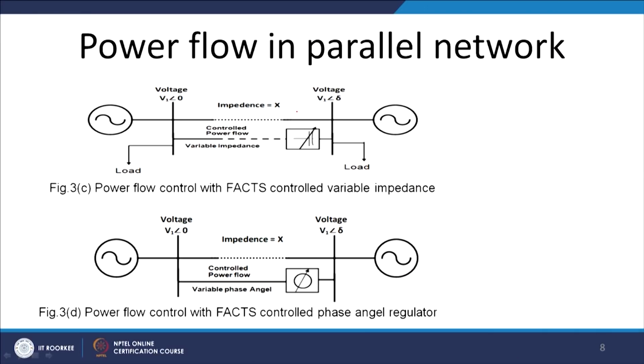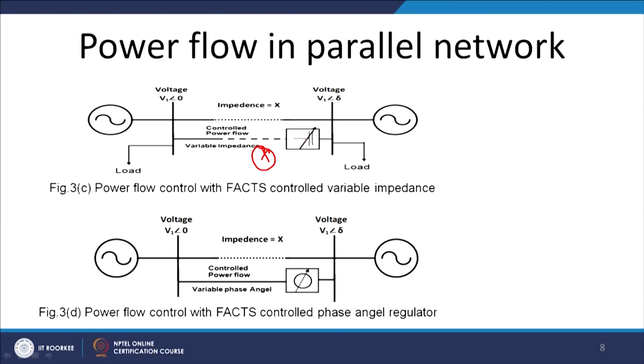In the same way, we can go for the solution with FACTS devices also. Let there be an uncontrollable line, the upper one, which may be the old one. Now we can place a new controllable line with a FACTS device. So this is a variable impedance. This variable impedance can be controlled, so the x amount of power flowing through this lower line is controllable, and thus 1 minus x should be limited to the thermal limit and other limits as governed by the authorities.